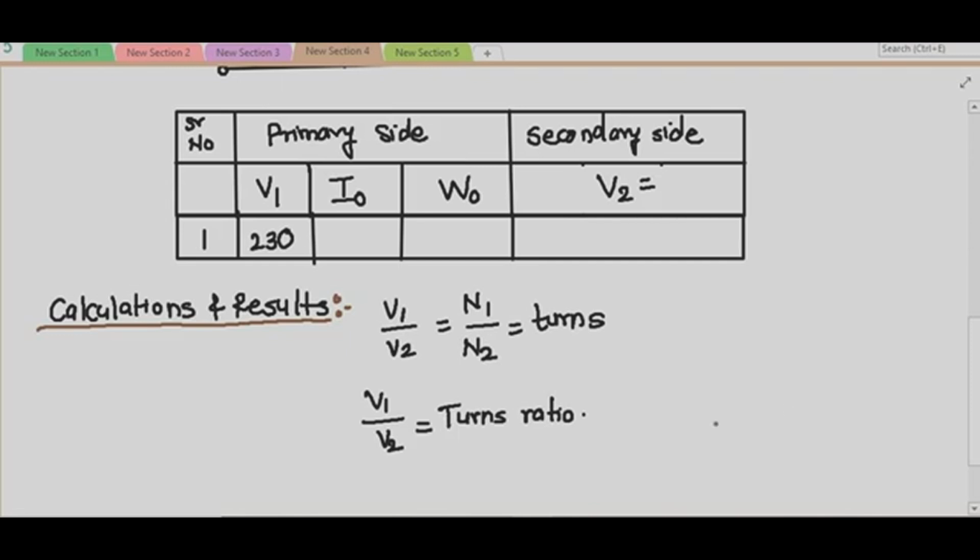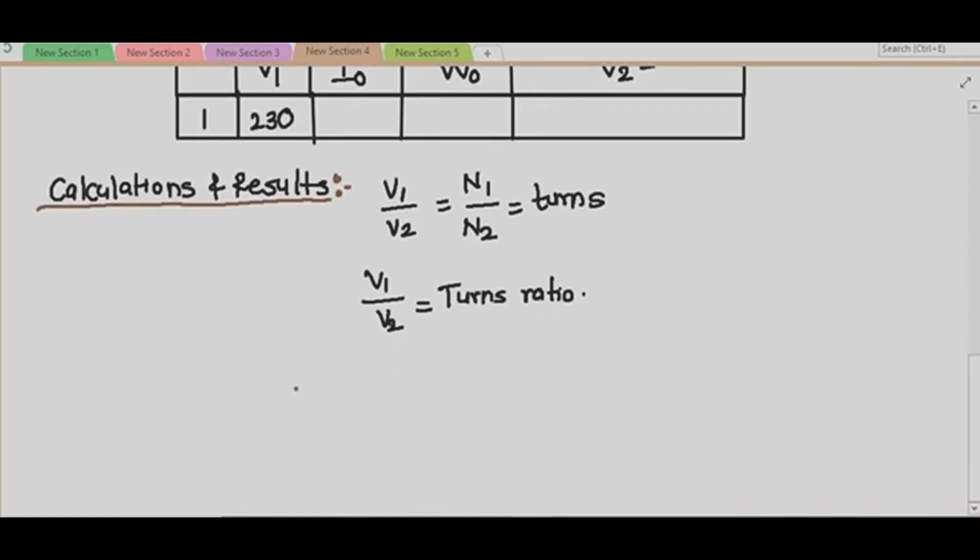The magnitude of your no load current I0 gives a check on the magnetic quality of the iron core and the joints.